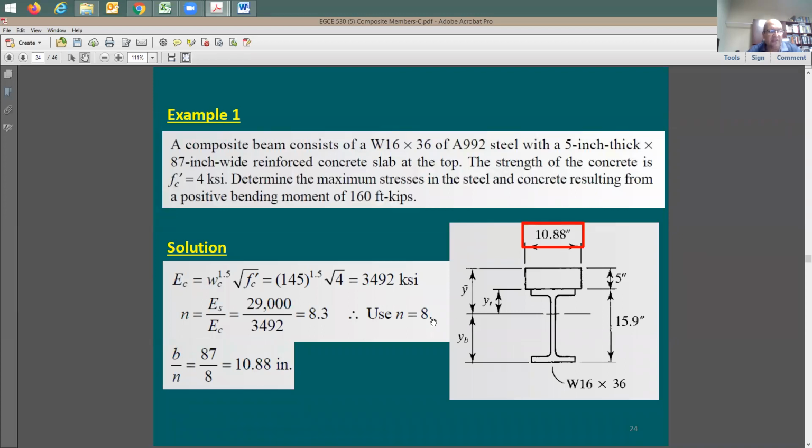Because the moment of inertia that you're taking here is going to be about the x axis. So the right way of doing it is to divide the width so that you keep all area elements at the same distance away from the neutral axis or the plastic neutral axis, if you like. So if you're doing elastic stress analysis, you keep them away from the elastic neutral axis, which is based on the centroid. If you're doing plastic analysis, you keep them at the same distance from the plastic neutral axis. So let's say for now we're working with elastic stress analysis, so we're going to keep them at the same distance away from the centroid of the section.